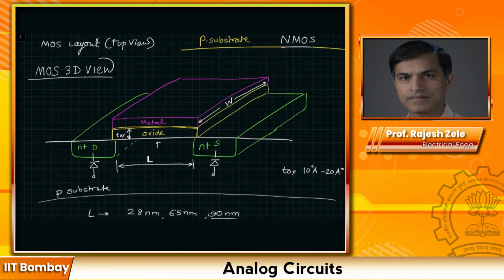As a result, sometimes metal is not overlaying completely on the source or drain regions, and then you will have a transistor that doesn't work. So to prevent that, you would have to have a large amount of overlap between the metal region and the drain and source region. So that was one problem.